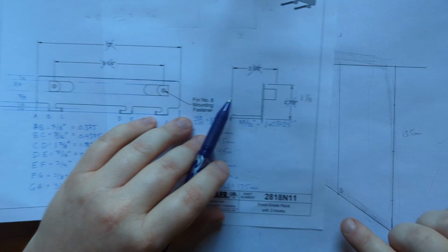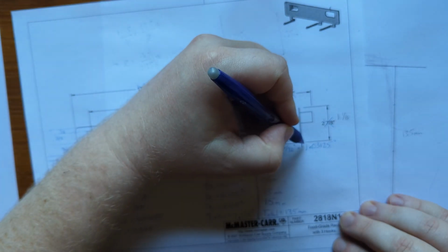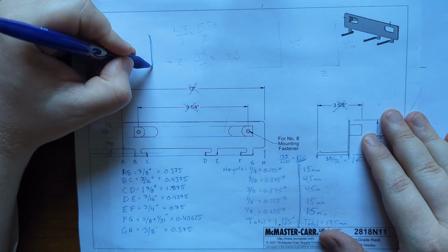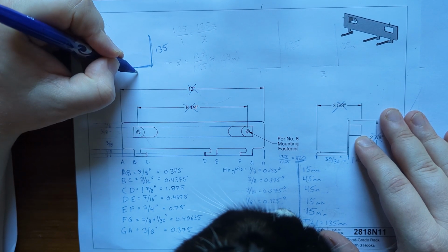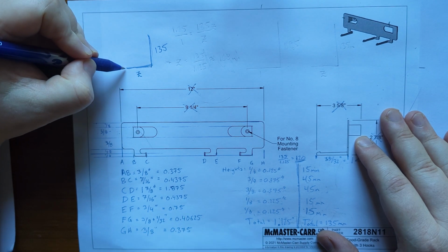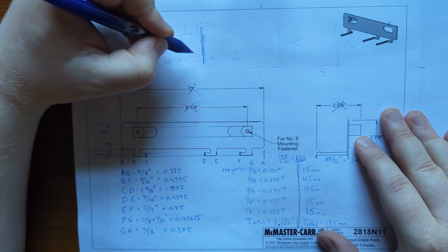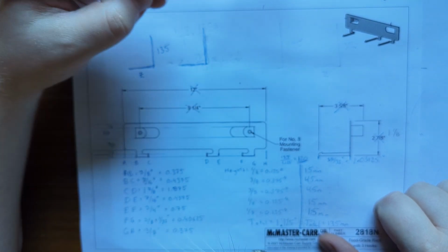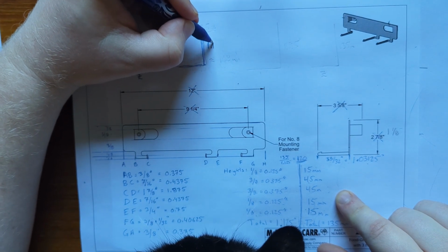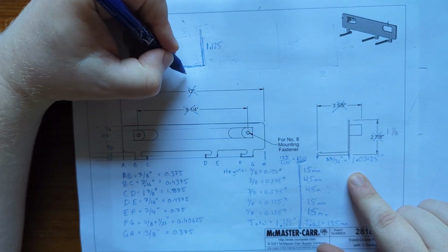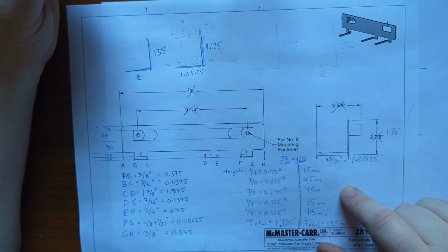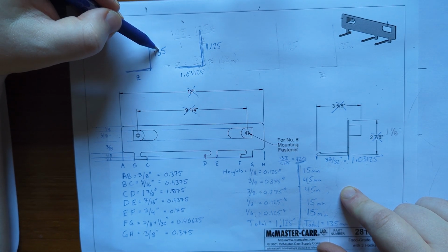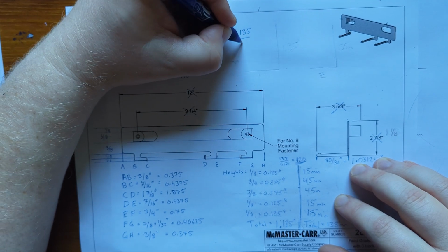In order to have this scaled properly, in our drawing, this height should be 135, and so our length can be that equivalent on there. This is the other way to think about what I did with the heights here. If this is 135, and we're trying to figure out what this measurement is, so how far it sticks out, I'll call that Z. Whatever that ratio between 135 and Z is should be the same as the ratio between the height and this length in the drawing. So this is 1 1/8, 1.125, and this sticking out here is 1.03125. Whatever the ratio between this height and this sticking out is should be the same as this ratio between this height and this sticking out. You can set up an equation like this.